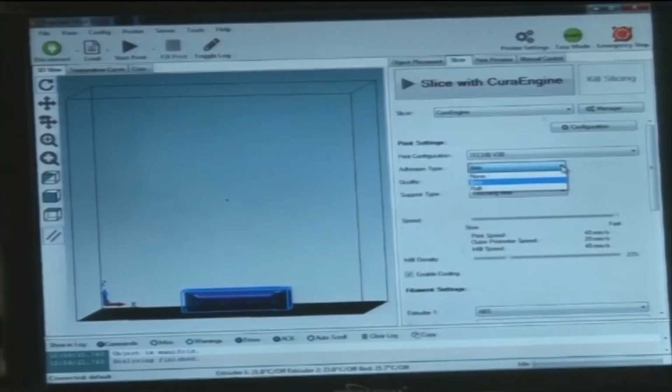About brim, what is brim? Brim, as I said, is just at the outskirts of the job. Brims are often used to hold down the edges of your part, which can prevent warping, and it also helps in adhesion with the bed.